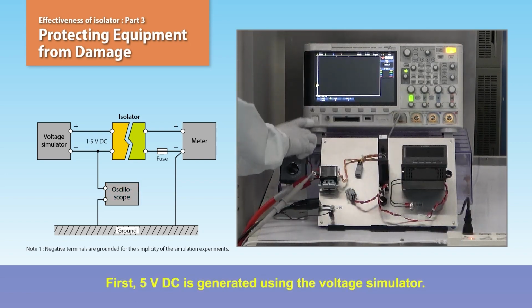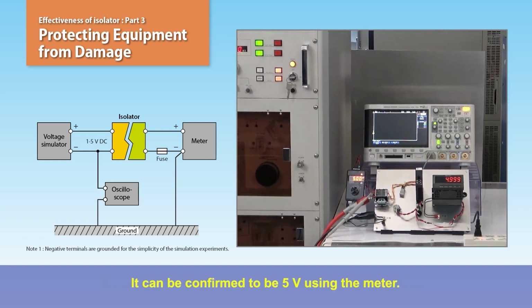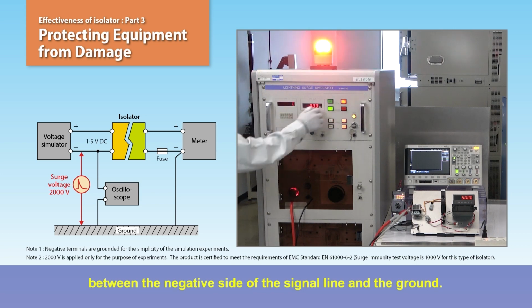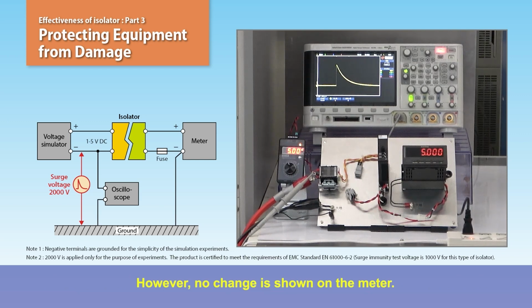First, 5-volt DC is generated using the voltage simulator. It can be confirmed to be 5 volts using the meter. Here, a surge voltage of 2000 volts is applied between the negative side of the signal line and the ground. A surge waveform of 2000 volts appears on the oscilloscope on the input side. However, no change is shown on the meter. This is due to the effects of the isolator.